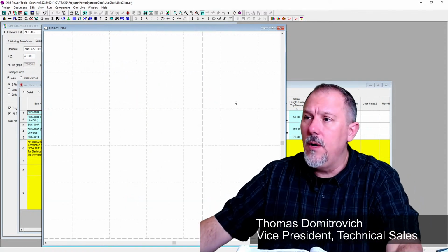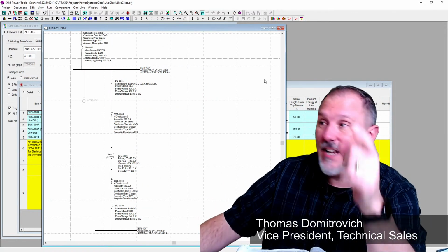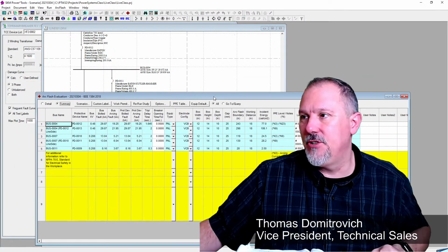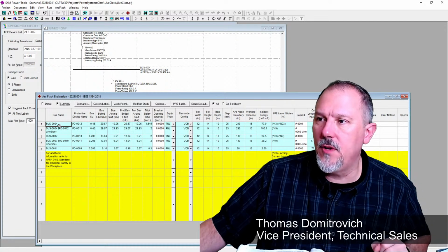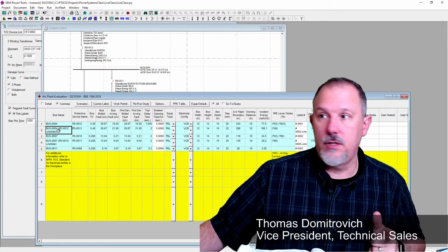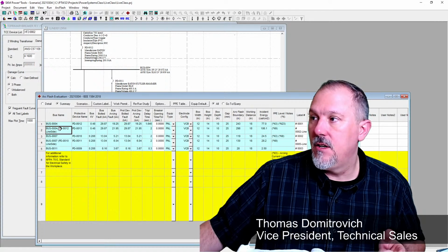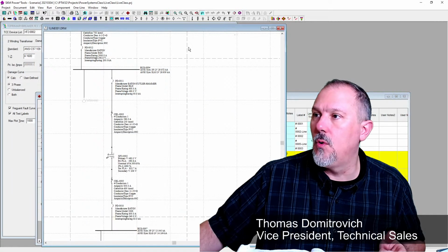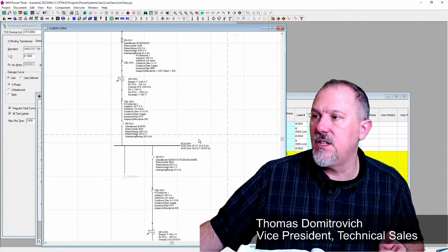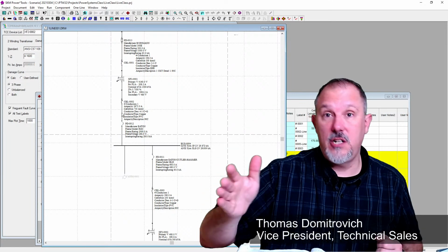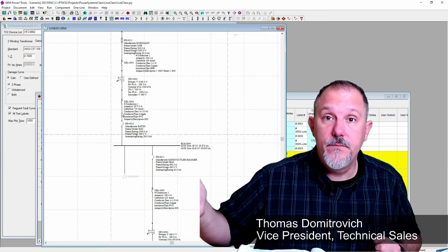All right, so we were doing the arc flash calculation. Now let's get back to arc flash, incident energy. What this is showing me, look, I've got two values of incident energy for each of these. Look at bus 4. So where's bus 4? Here is bus 4, the first panel board on the secondary of this utility transformer. I'll call it the utility transformer, but it's a transformer.